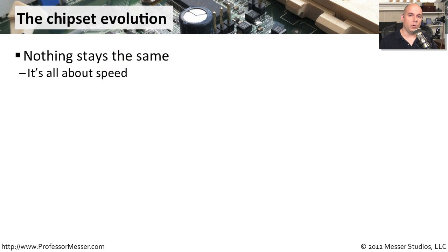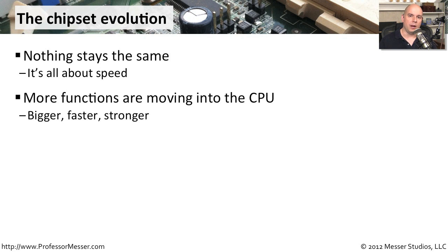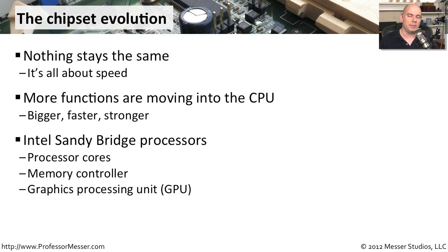As we look at our motherboards and we think about the logical layout of the Northbridge and the Southbridge, what you'll find is through the years, things have changed a bit. We've been able to make our processors much more efficient. We've been able to add additional capabilities to our processors. And some of the things that were separate chips like our Northbridge, or separate interfaces like our video that was built into our system that connected to our Southbridge, we're now putting right onto the CPU because now our CPUs are much more capable.